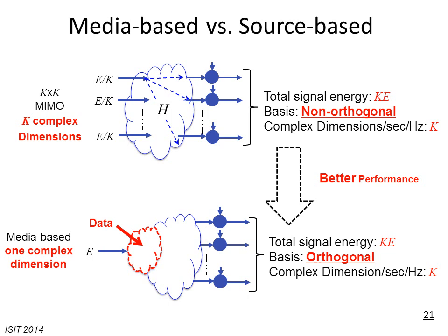Please let me also clarify one point: by the term energy harvesting in this presentation, I have been referring to the fact that, for example, in a MIMO system, when you send an energy of E divided by K over each transmit antenna, the energy received at each antenna will be K times increased, because it receives energy from all transmit antennas.